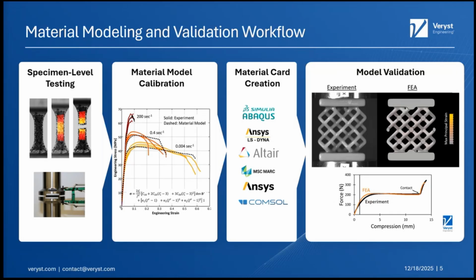When should you complete cyclic loading versus just simple uniaxial tension testing? To me, it's less about plastics because basically all of them are going to show those kind of relaxation and unloading and reloading effects. The question is really, does the unloading or multiple loadings matter for your application? So if you're never unloading it, then you don't care. But we'll talk to people and we're doing some impact simulation and testing, and I recommend these cyclic tests and they say, well, I don't care about cyclic tests, I just hit this thing and that's what I get out.